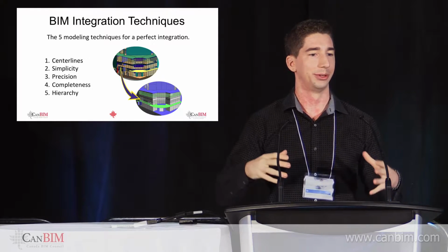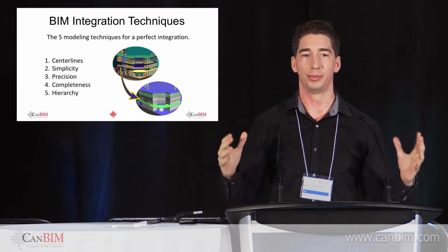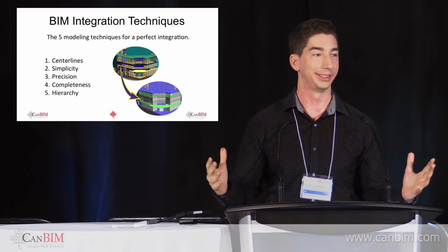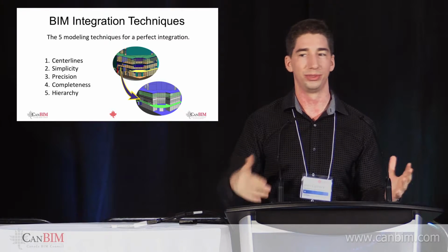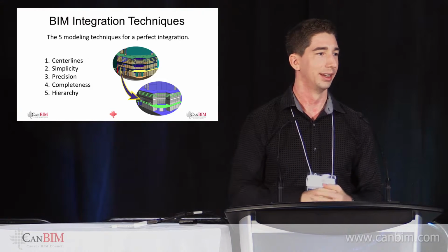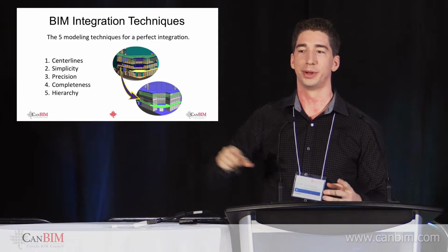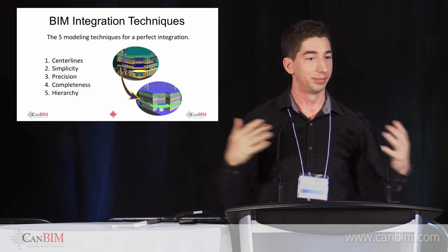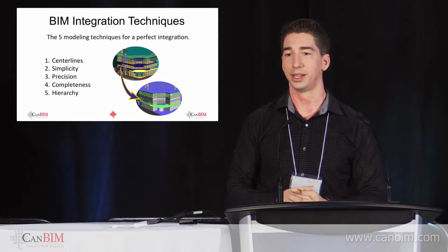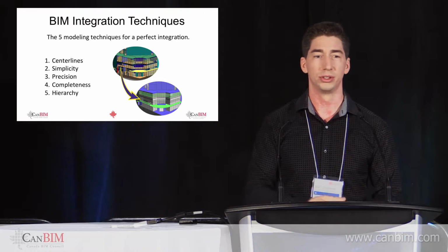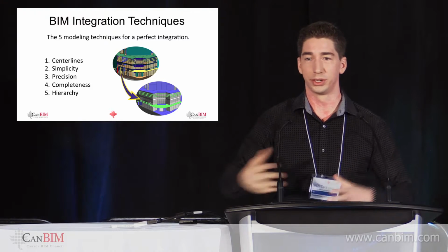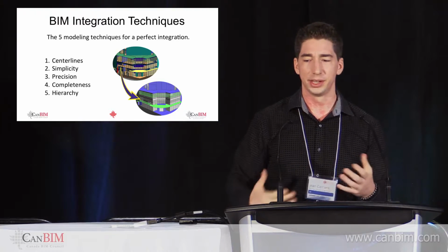Imagine filling up your building with water, and the entire building would be full, and there are no leaks, so nothing's going to spew out. So if you've got these weird little bulkheads, the water is going to go out through those bulkheads. So what I usually do is I delete them, or turn them off, say non-room bounding. Your structural columns, again, spaces, we're going to go around that. So that's kind of the idea.